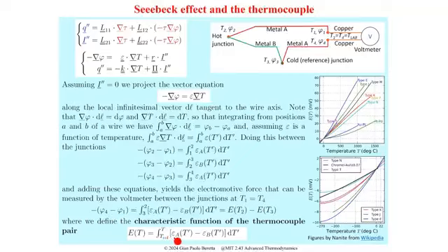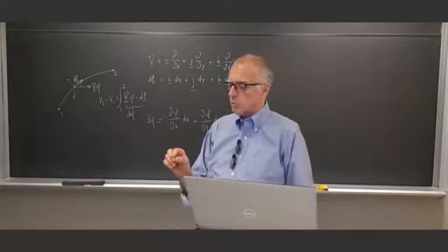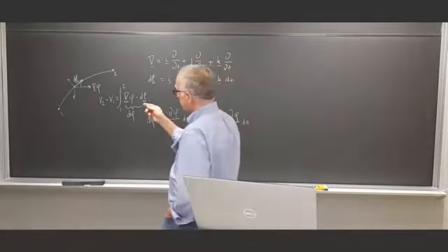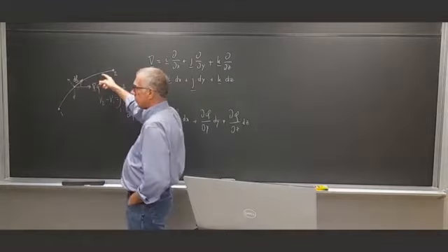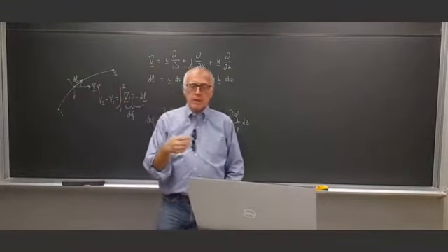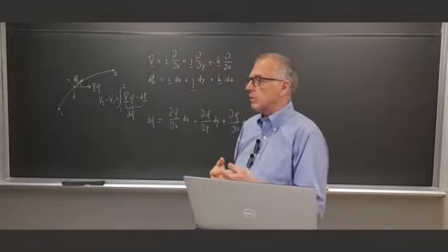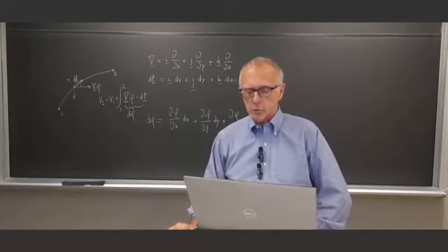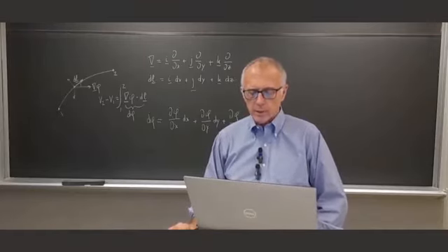Because, yeah, you could do it theoretically, but small variations in the cross-section of your material, or some impurity along the wires, may result in different features and properties of your wires. So we always need to do a calibration for your thermocouple.